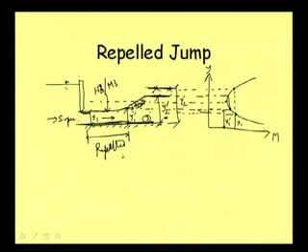And that way, engineers are taking different measures. Sometimes they put a rising portion somewhere upstream, so that the water depth will be rising and the jump will occur before reaching this particular point. Different devices are there which try to contain the hydraulic jump close to the upstream structure, so that the concreting or safeguard required is less, and that way our cost is less.